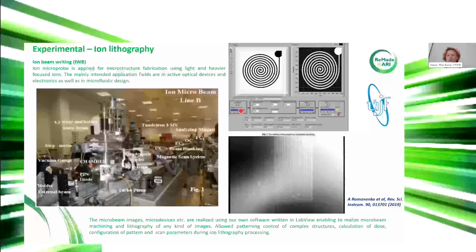So this focused ion beam can be used not only for ion lithography, modification and creation of microstructure with high current, as I mentioned before, but it can also be used, after the deposition, for checking what the elemental maps are in such a structure. This is not a microstructure. This is porous polydimethylsiloxane, which is a special polymer with silicon, mixed with graphene particles. And you see that these porous materials are very prospective, for example, for sensing.